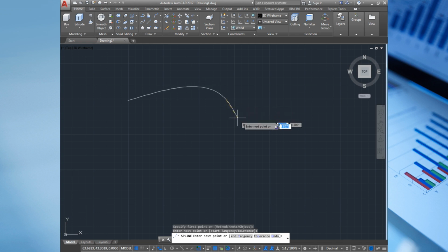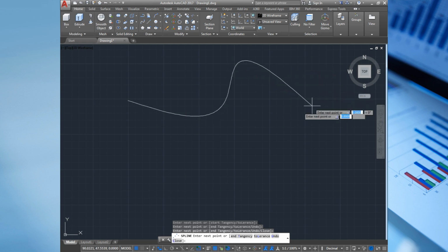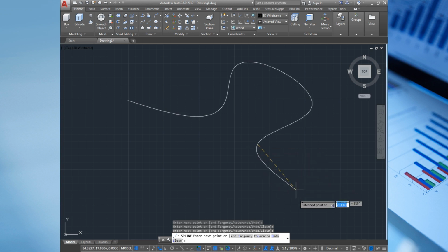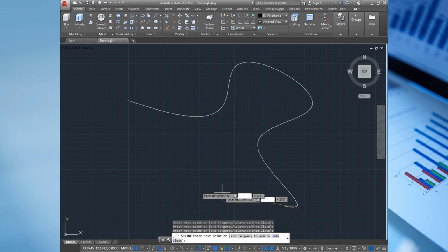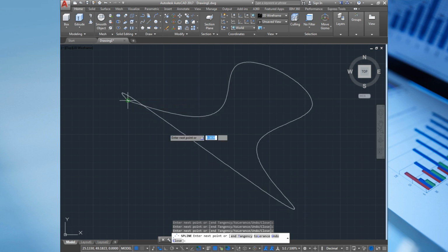When we bend the line, it either creates a curve upward, or if you take the line upwards, it creates a curve downwards. So mostly this is used to create curves according to how you will draw. That is the spline tool. At the end, you can either connect it back, or you can click escape to disconnect.